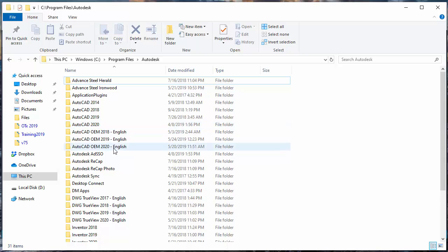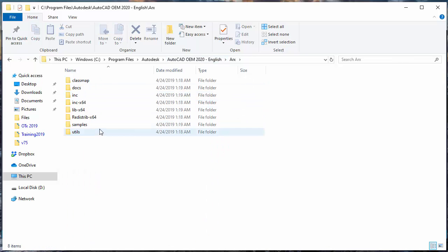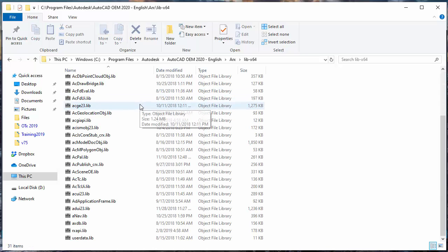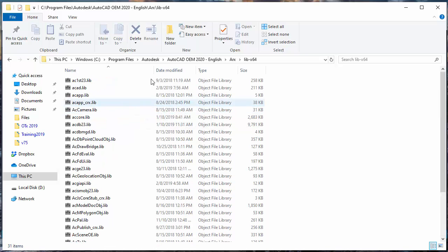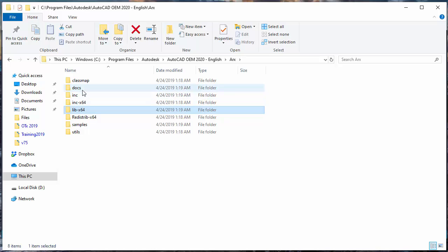The ObjectARX SDK is included with the toolkit and is specific for OEM. To target the OEM host environment, you need to build with this version of the ObjectARX SDK, although the API is identical to the vanilla AutoCAD ObjectARX. The libraries linked with your modules and target runtime modules are different and specific for OEM.